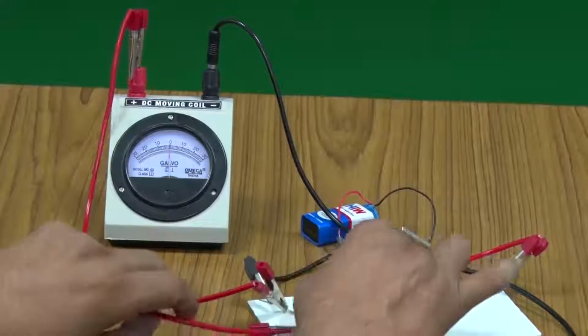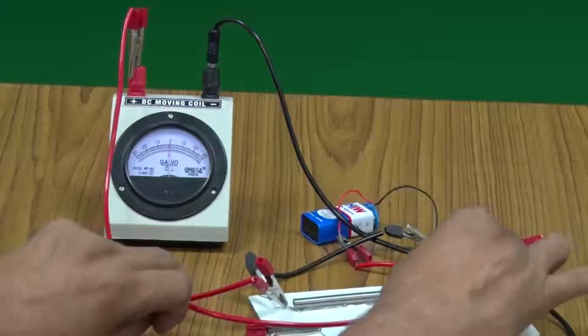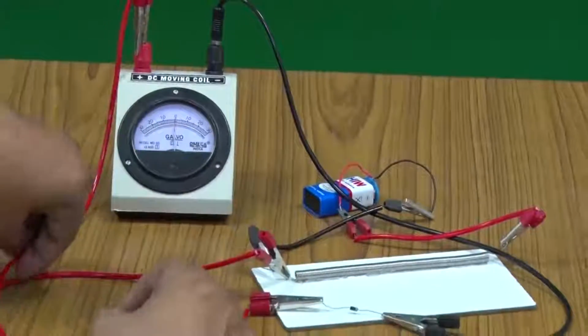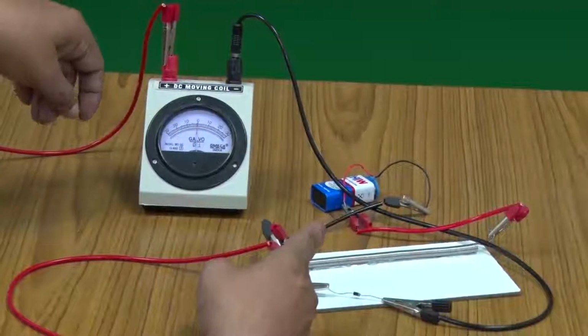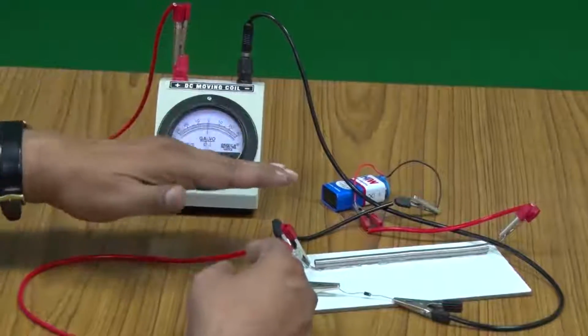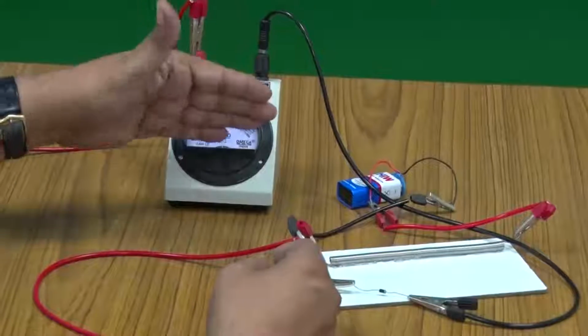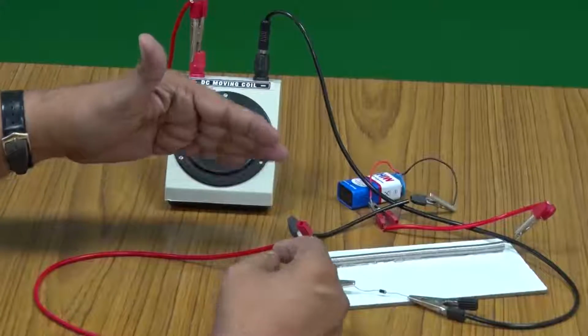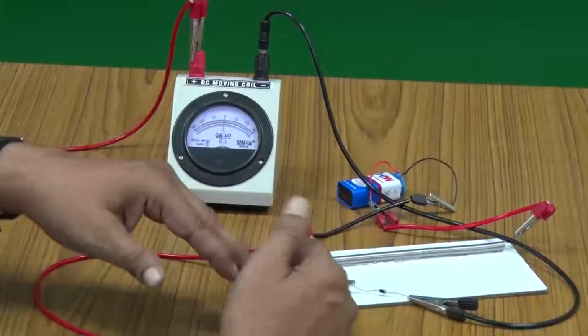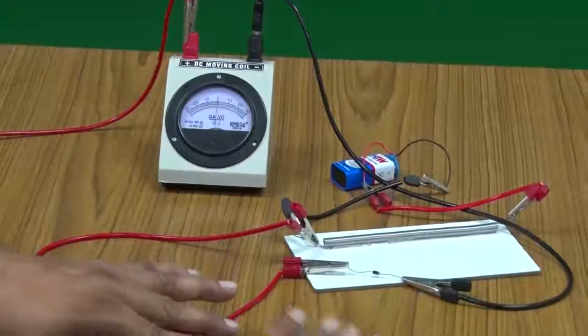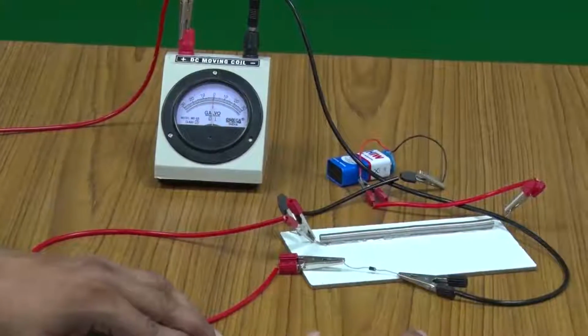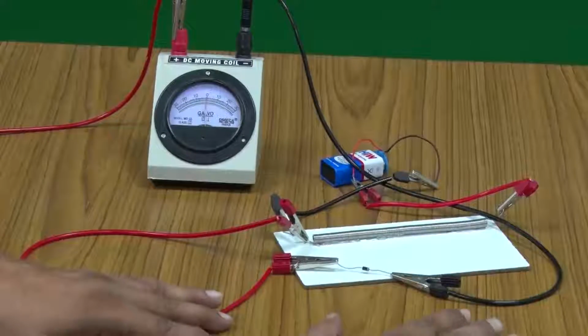So, whatever voltage you apply, you do not have a current in the reverse bias, whereas in forward bias you saw that if you apply some sufficient voltage, then you have this current. So, the diode offers low resistance in forward bias, and the diode offers very high resistance in reverse bias.